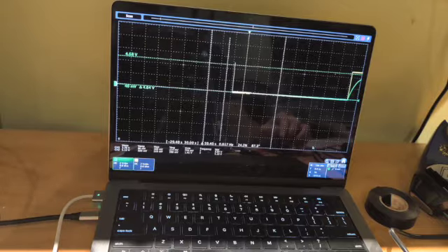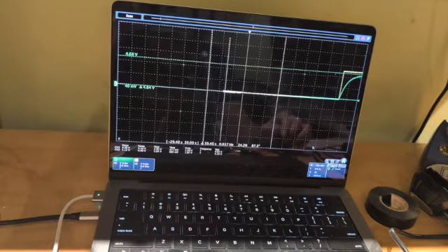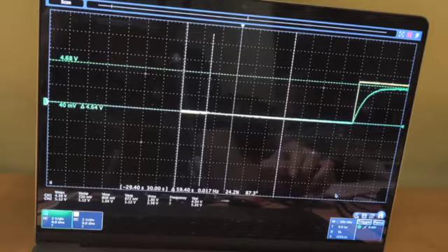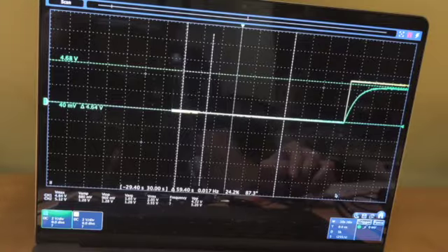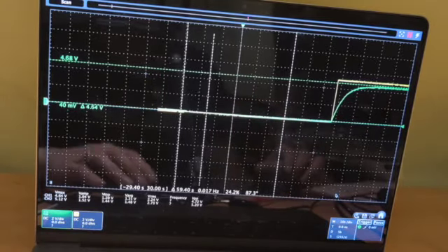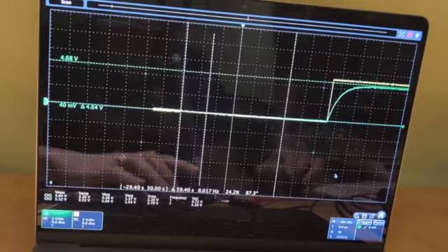Just so you can see, the yellow is the supply voltage. It's constantly at about 5 volts. So now the capacitor is rapidly charging, and now it's evening out. It's reaching the top, and I think due to some losses, it's probably not going to reach the top there. So let's just pause it here. I think it's never going to reach the top, and it's essentially finished charging.